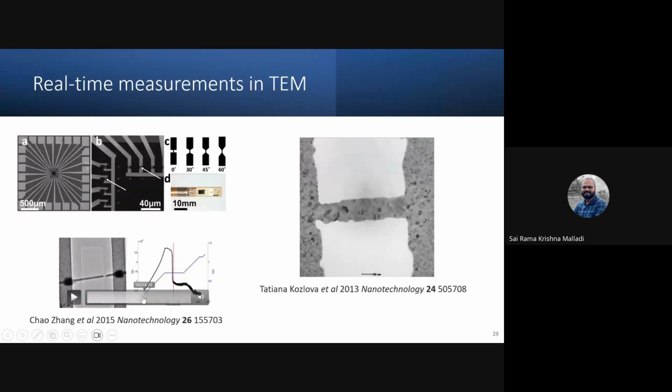So if I zoom in here at this particular point, there is formation of a little cavity here. And then when this forms, what is interesting to note is at the bottom left corner, there is another feature which is developed. So in indium arsenide nanowires, we've observed that there is a phase separation, or separation of arsenic from indium, and the nanowires start breaking down.